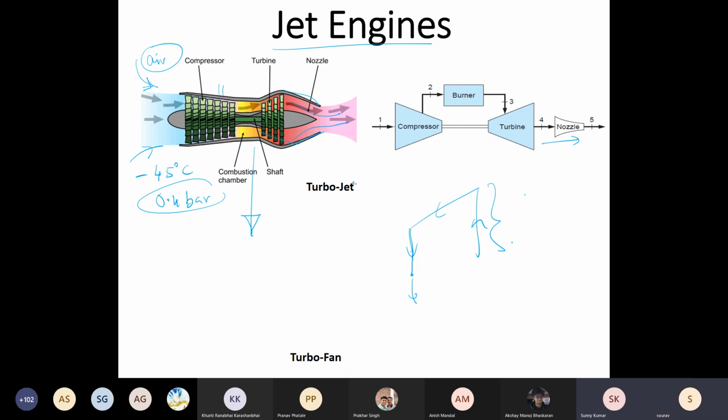So that's the idea behind using the reverse Brayton cycle and not the VCRS cycle, because you will have to carry the entire refrigerant pipeline, condenser, evaporator, everything. You will require heat exchangers there. It is going to be a closed cycle, your VCRS cycle. Here, since air is the working fluid, you can just use it like an open cycle.